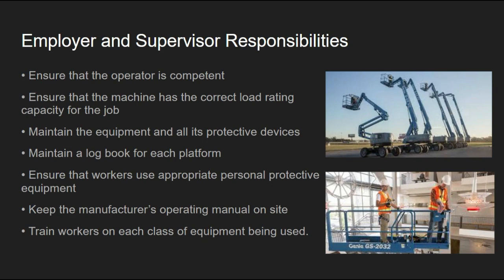The employer puts a supervisor in charge. So that person's got to make sure that the operator who's going to be using it is competent, know that the machine has a correct load rating capacity for the job, the equipment has to be maintained, and all the protective devices that go with the equipment are maintained.